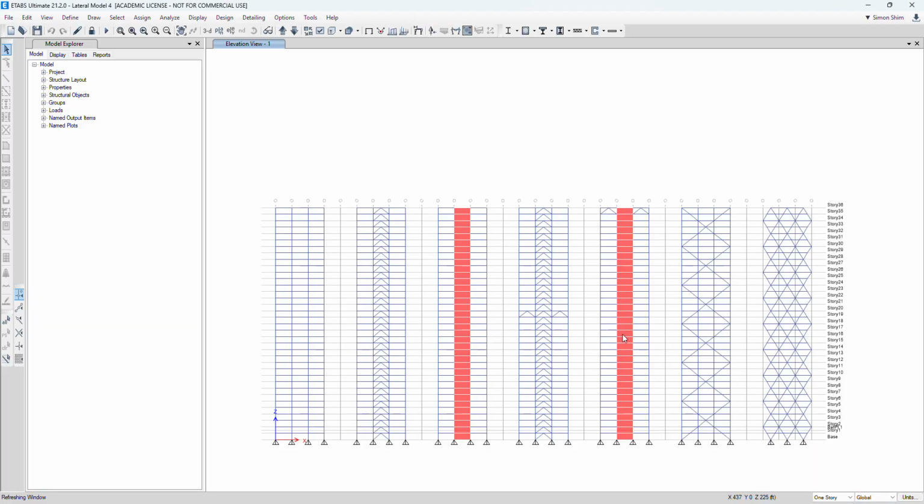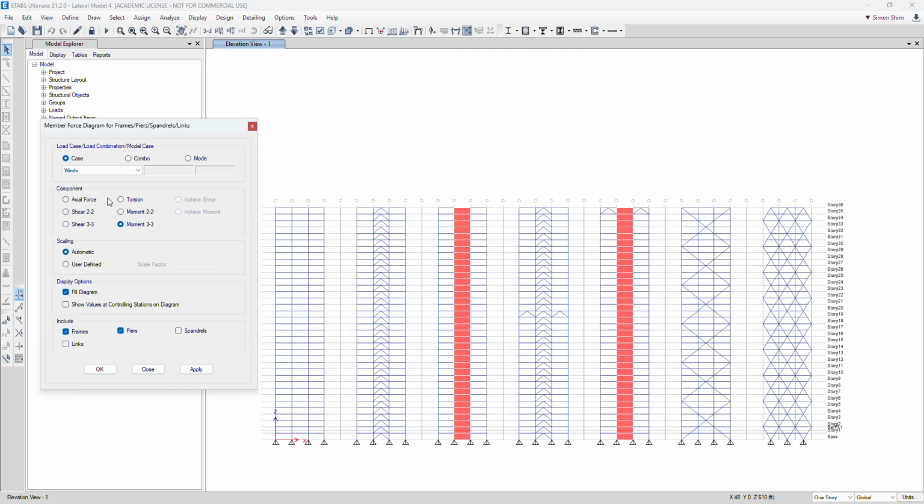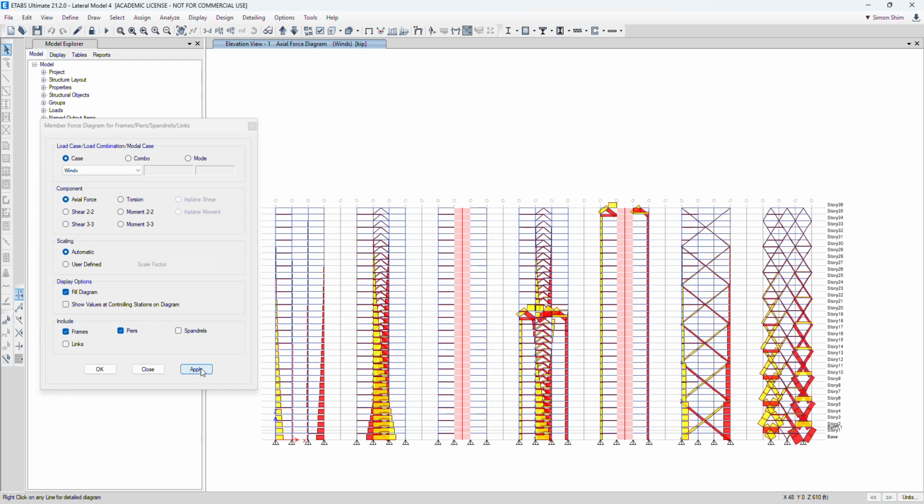Pretty much like this, right? While this one is running, let me just see. So basically, we adopt either this type of system. Under the wind loading, the concrete core wall or just braced frames take the majority of shear and overturning moment. But when the floor hits this outrigger truss, load is redistributed here.